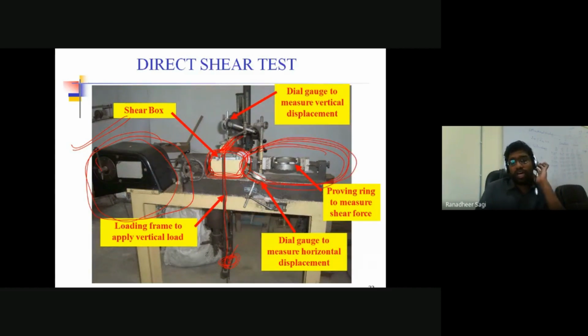So, for ensuring that constant deformation happens in the soil to undergo failure at the surface of contact between the soil of the top split half and the soil of the bottom split half, how much reaction gets developed in the soil is understood by reading the data from your proving ring, provided here. During the complete test, you also have dial gauges fitted to your test setup. You can see one dial gauge fitted in the vertical direction, and another dial gauge fitted in the horizontal direction.